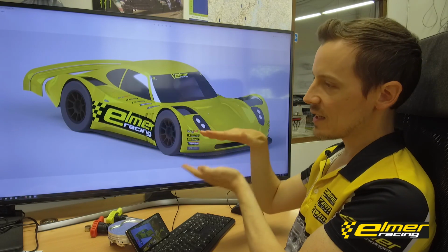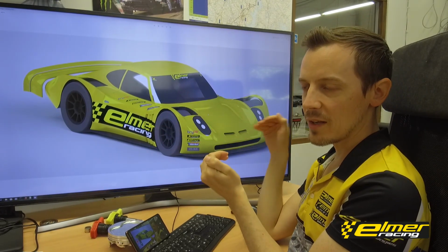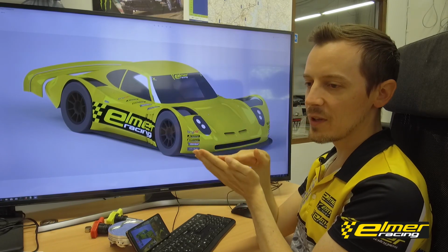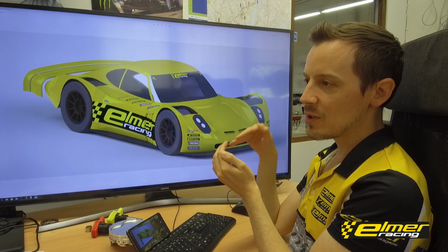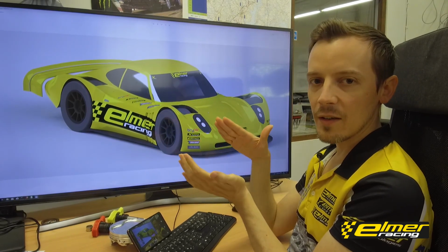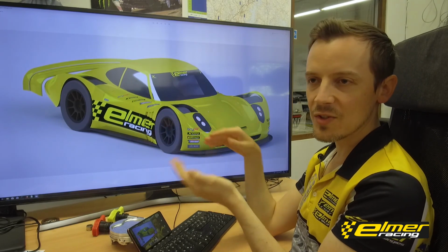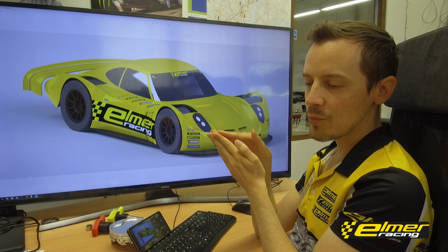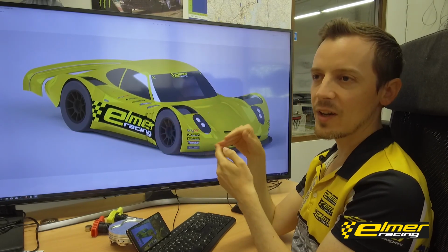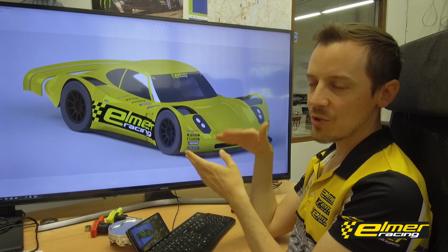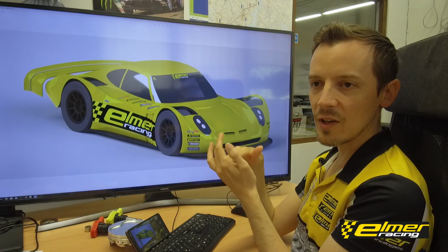So basically a free stream wing produces pressure differences by both deflecting air and creating velocity differences. When you deflect air, of course air has mass and momentum, so you need a pressure to change the direction of the airflow, and you can create pressure on your wing surface by that means, and then also with the flow velocity.